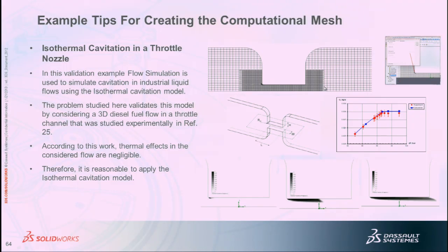compression here and expansion. Now cavitation, if people are familiar with it, we're actually taking a liquid and it's turning to a vapor because the velocities are so high that it's actually boiling at that point. And so you have two-phase flow in certain regions.